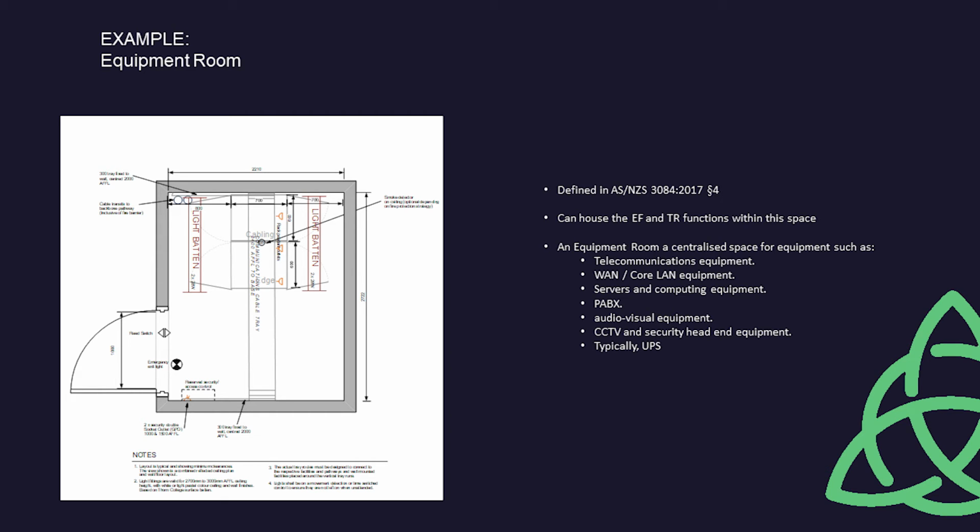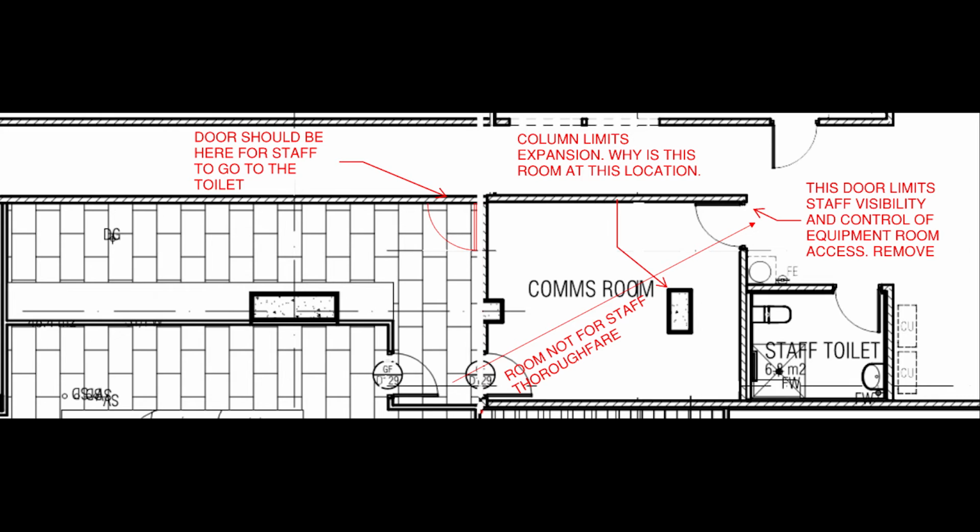The indoor noise level created by the air conditioning system, as measured with other systems switched off, must not exceed 60 decibels. The indoor unit must not be located above equipment racks or wall distribution frames to ensure that any leaks during the service life of the air conditioning system do not put equipment or interconnections at risk. Before anyone forgets, protective cages should be provided over any sprinkler or fire suppression heads inside the room.